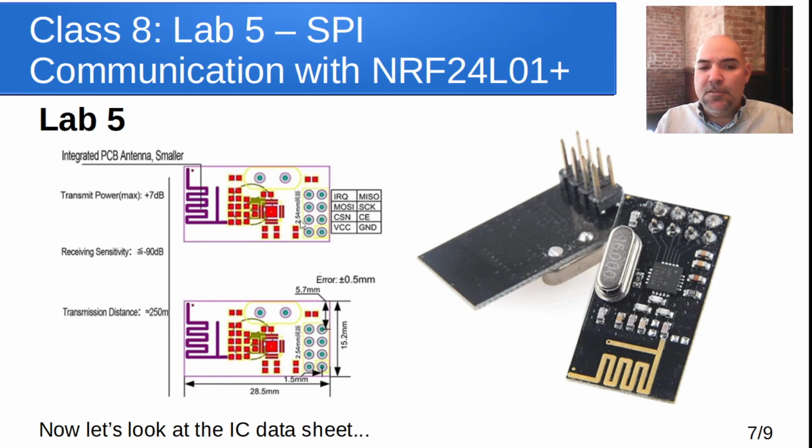The biggest source of power draw from this is having the receiver parts of this chip on and listening to that line and amplifying things. So this chip itself has a way to turn on and off just the radio part, or select it to talk to it and communicate with it. In our case, we're not going to have to worry too much about that right now.